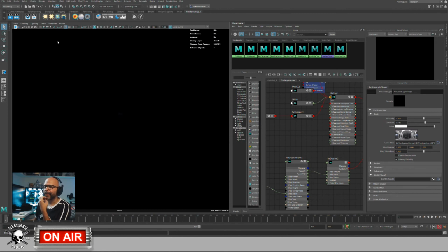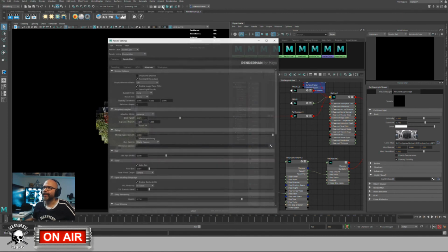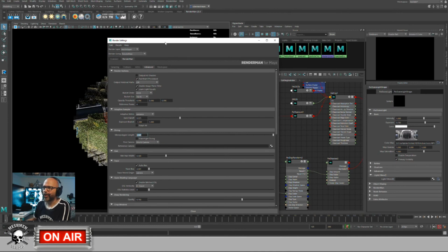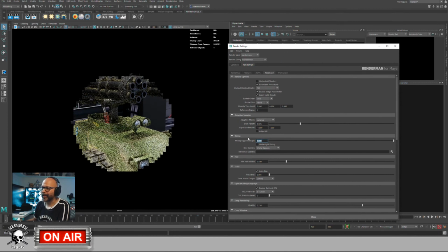You also have something in the old Renderman render called shading rate. That's not applicable now with the new Renderman, but you have something similar when it comes to displacement, and that's the option to set if you want more out of your displacement. It's called micro polygon length, and you can play with that. If you decrease it, I believe it gives even greater fidelity. If I set this to 0.5 or something, it's going to be even more diced, essentially subdividing the mesh even further.